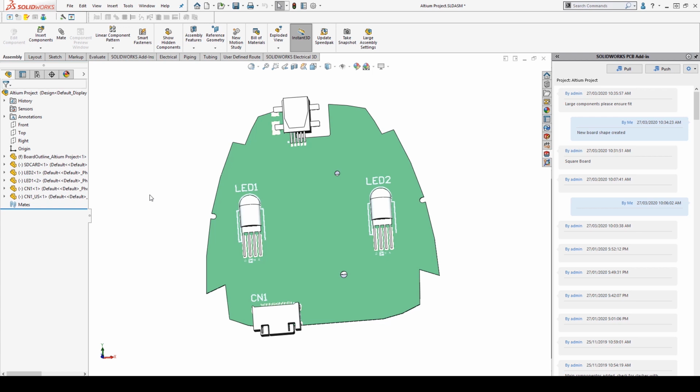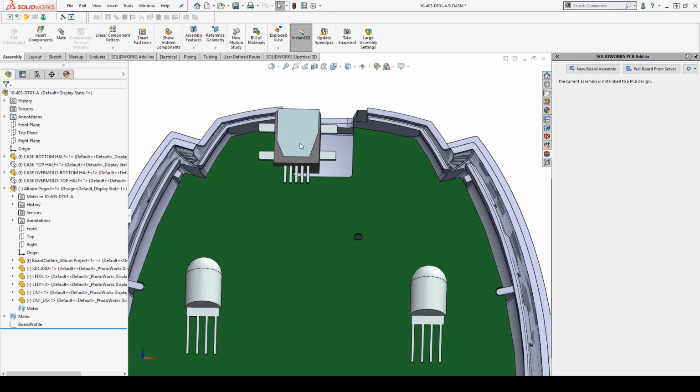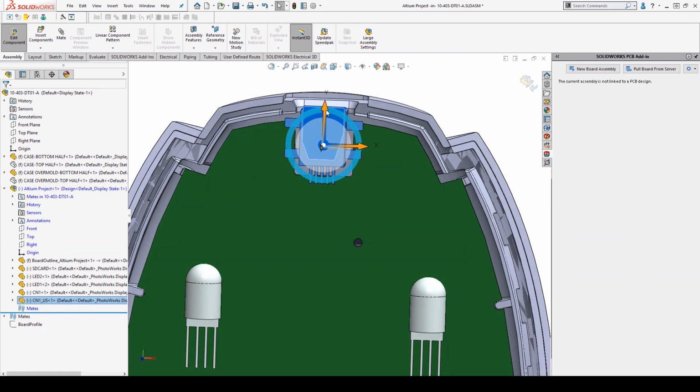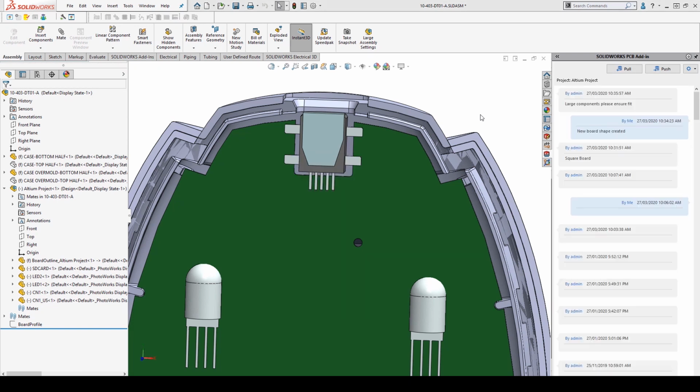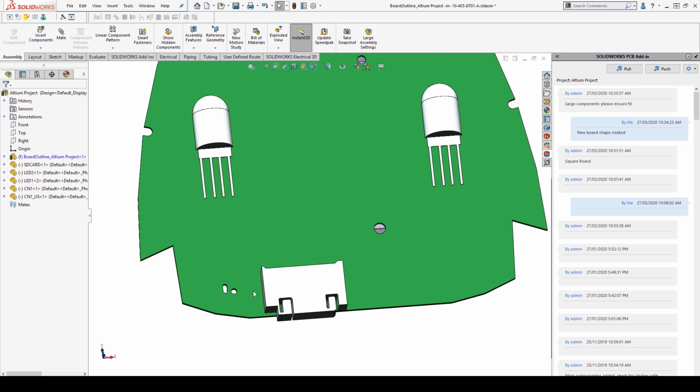So moving on then, let's move back to the top level assembly, and we can move components from here. So let's turn off those decals, and let's say I want to edit my assembly, and I want to just shift either by dragging, perhaps using my triad here, just move that to a more suitable position. We can also do a similar thing from the subassembly, so I could drag maybe this component here, release it, and all of the holes can rebuild and move with the component. Okay, so it saves you having to worry about doing that as a separate step. It's all nice and neatly kept up to date.